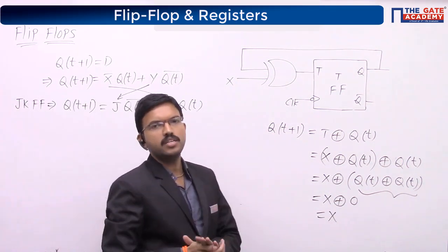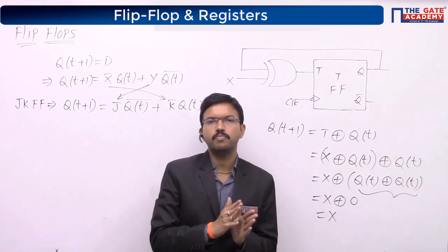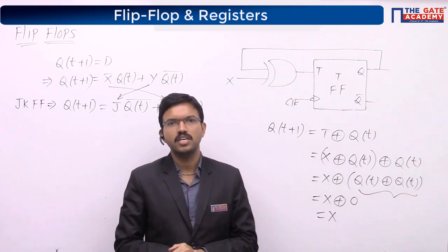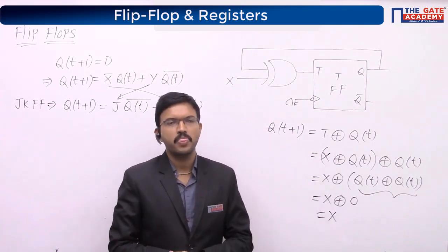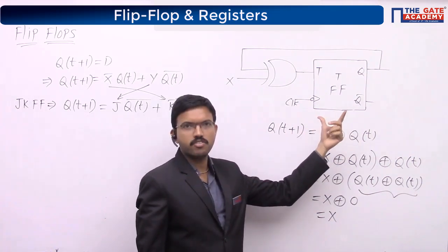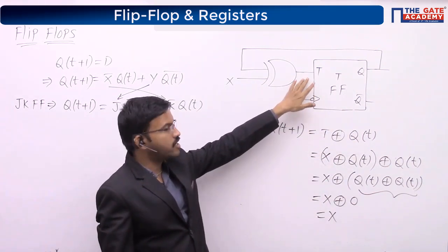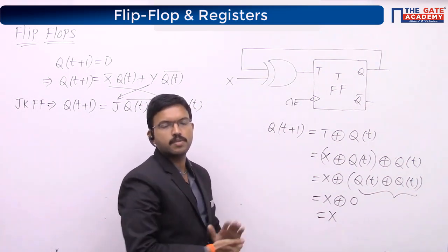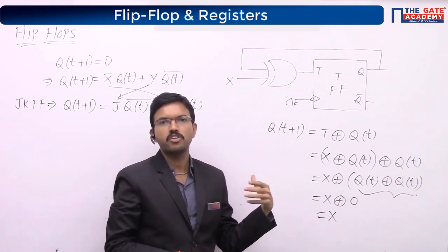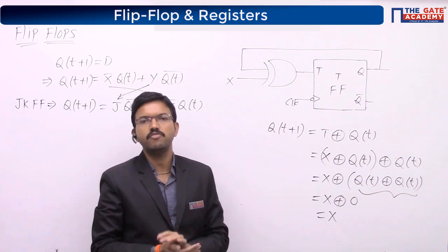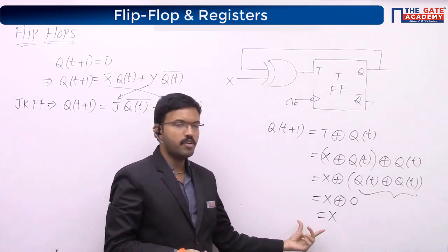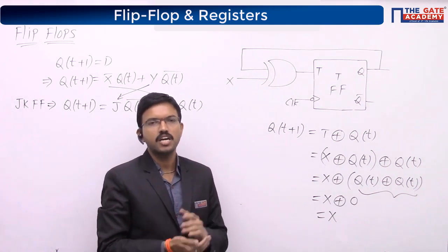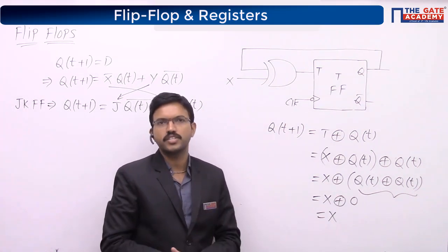You don't need to remember how to convert one particular flip-flop to another. Okay, he will give some particular flip-flop and some logic gates and ask what the overall circuit is. First, you have to write the characteristic equation of the given flip-flop and then, whatever inputs you have, find them and substitute, and from that you will get the resultant simplified equation, and then check with your known characteristic equations. Here we have 4 flip-flops. Whatever simplified equation you get, just check it against those 4 flip-flops' characteristic equations. From that you can choose the correct answer.